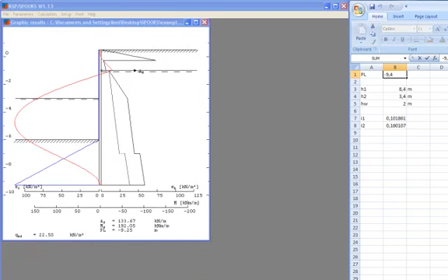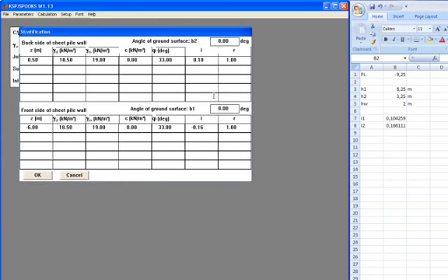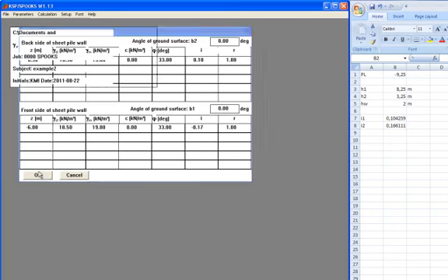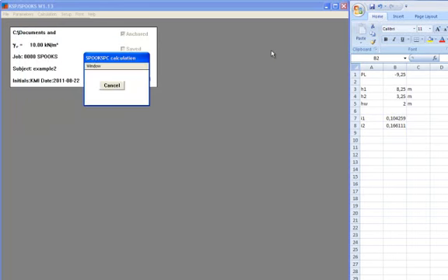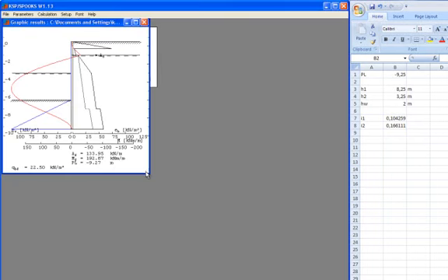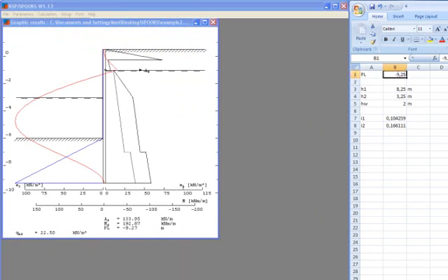We go back to the Excel spreadsheet, enter the new value for the driving depth, and we see slightly changed gradients. Again, go back to SPOOKS, enter the stratification tab to put in the new changes in the gradients. Press OK and calculate the project once again. The results show now only a slightly larger wall.